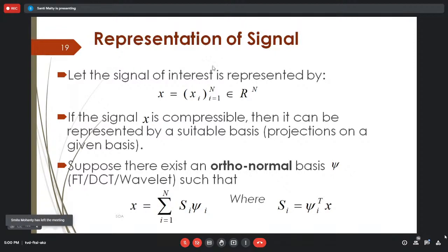Similarly, you have n-point data here. Suppose you think of a representation space. Let's say this is the Fourier basis, e to the power minus j omega t, multiplied with the time function g(t), or xn or gn, the discrete sequence. If you do a summation operation, this is your Fourier coefficient, and when you do the inverse Fourier transformation, you can get back the same. So this is your Fourier transformation. This is the Fourier coefficient. Here you can think of your representation.